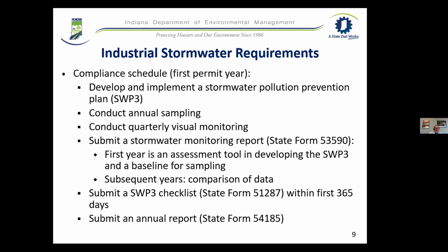So when that happens, when you get the permit coverage and you submit your NOI, you should start to develop and implement your stormwater pollution prevention plan. That first year is really when you need to focus on development of that plan, evaluating.